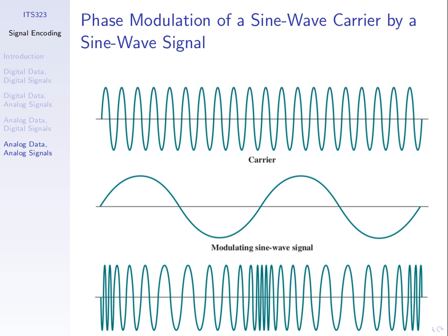How do they prevent them from interfering? So there are regulations. I can't remember the exact bandwidth, but I think a bandwidth of around 20 kilohertz. From the center frequency, you're allowed to transmit a signal from plus or minus the center frequency, such that the bandwidth, the difference between the minimum and the maximum, is 20 kilohertz.